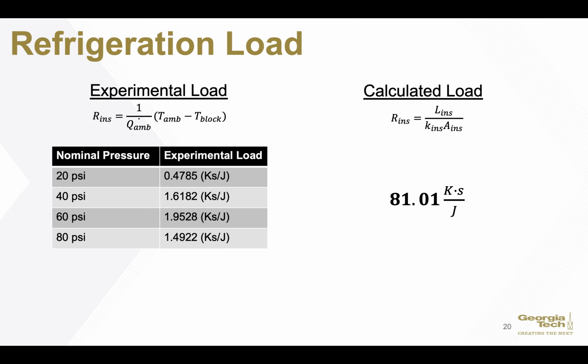By comparing them, we can observe that the experimental value is quite off from the theoretical result, by an exponential amount. This might be due to the assumption we made in the calculation for the heat transfer rate due to ambient heating. At steady state, we assume Q load equals 0, so then Q air equals Q ambient, and real-world examples might not be so ideal. Another explanation might be that the friction during the airflow might also stop some of the heat transfer from being entirely calculated.